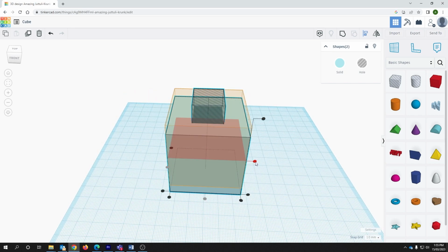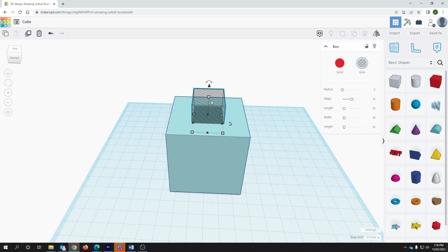If we click this align here, this will place the empty space or the hole in the middle of the cube. In this case, we don't want to do that. In this case, we want to cut this hole out of the cube. We do need to have part of this hole protruding from the top of the cube, so we won't align the third axis. Instead, what we'll do is single select the cube again and manipulate its size using the arrows.